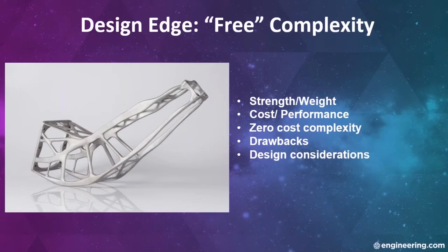And post-build processes are different for additive components compared to castings, weldments, or machined parts. Just holding a part like this for machining may require custom fixturing or specialized machining techniques to minimize distortion. Now, for designers who don't have the luxury of advanced simulation capability, it may be necessary to iterate, test, and break parts like this until the performance targets are achieved. For non-critical assemblies or assemblies that can be approximated with commodity materials, that's a viable strategy. And the ready availability of additive-as-a-service vendors means it's possible for an engineer to experiment with this technology without making that heavy commitment in hardware.